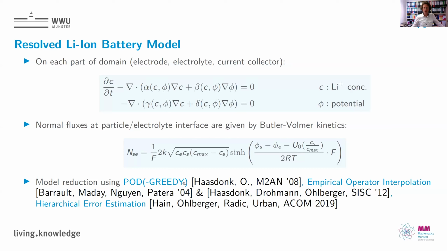If you tackle these problems with the state-of-the-art reduced basis methods, then we can use the so-called POD-greedy approach. So you use a greedy approach to select a parameter where you compute snapshots to compute the reduced space, and you use the proper orthogonal decomposition, which was also announced by Gianluigi Rozza, to compress the time trajectories and get only the most relevant information into your reduced models. This was introduced together with Haasdonk in 2008, and there is also a priori analysis available from Werner Haasdonk. For the nonlinear treatment, we use empirical operator interpolation or discrete empirical interpolation, which was also announced.